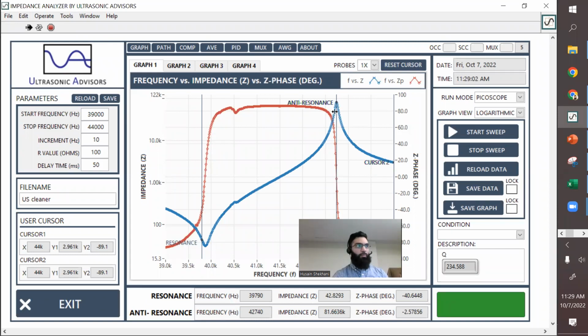One really important point I want to point out: for a lot of devices, like a lot of bending devices or non-symmetric devices, the resonance frequency sometimes has a lot of spurious modes around it. So this is like an expert tip here: when the resonance frequency has a lot of spurious modes around it, sometimes the anti-resonance frequency doesn't. And in that case, you can use the anti-resonance frequency as a standard for measuring the quality factor. It'll give you a consistent value. Now, it's slightly different in some physicality than what you're measuring at resonance, but it's consistent and it's derived from much of the same properties.